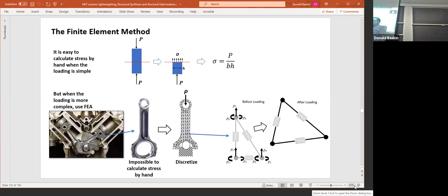And then you've got this complex loading condition, because of these point loads and the fact that it's not always completely two opposing forces. Sometimes there's a moment on there. It's far more complex to understand what the stress is on this part, and therefore it's more difficult to choose a material, a cross section, a fatigue limit. It all becomes much more complicated. So that's why we have finite element analysis.